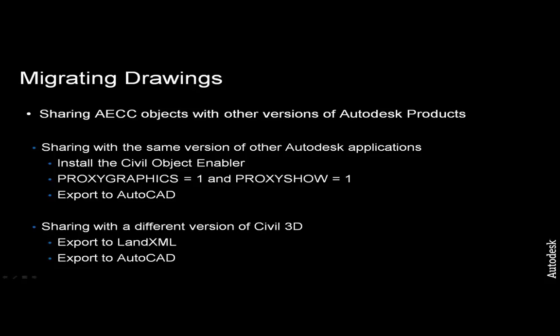Another option is to use proxy graphics. Setting the system variable proxy graphics and proxy show to 1 will allow you to save a drawing and open it in another Autodesk application and display the civil objects as proxy graphics. Unlike the Civil Object Enabler, you will not be able to select or report on the civil objects in this drawing, however.